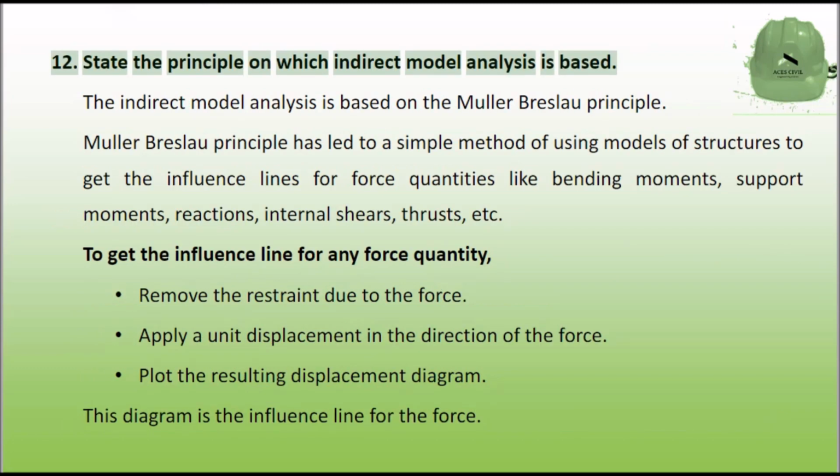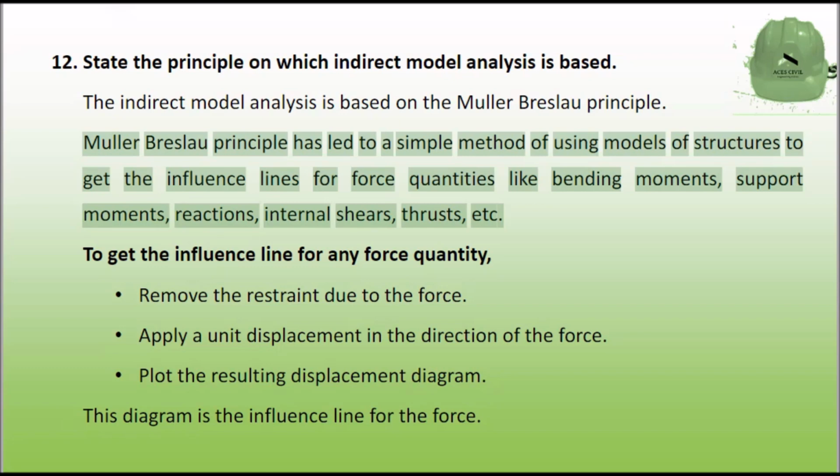State the principle on which indirect model analysis is based. The indirect model analysis is based on the Muller Breslau principle. Muller Breslau principle has led to a simple method of using models of structures to get the influence lines for force quantities like bending moments, support moments, reactions, internal shears, thrusts, etc.